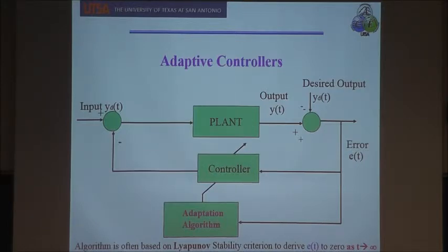All these control algorithms, which I should have mentioned earlier, are based on a mathematical model of the plant. I repeat, the control algorithm is based on the mathematical model of the plant. That means you're bringing physical principles, Newton's law, thermodynamic law, energy conservation, etc., applying them to your plant, and you come up with a mathematical representation.